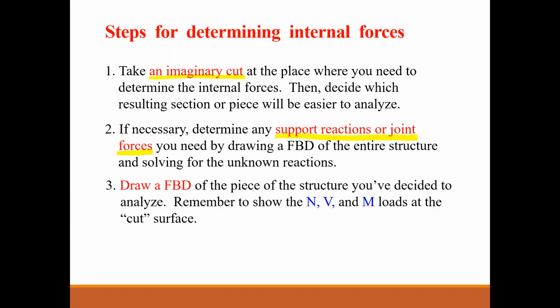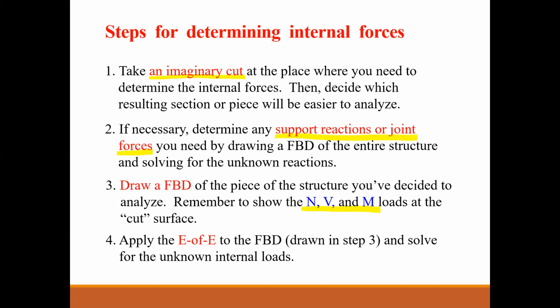As always, after we find the support reactions, we draw a free body diagram for the piece of structure that we want to analyze and show internal forces and bending moment with the correct direction. And the last thing is to apply the equilibrium equations to find the normal force, shear force and bending moment. So we're going to solve an example and see how we can find these internal forces.